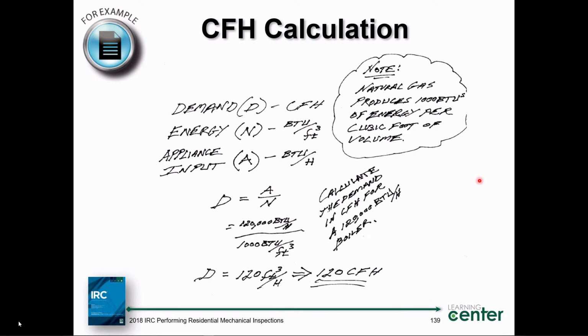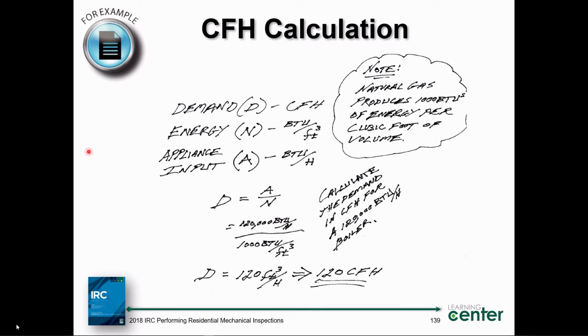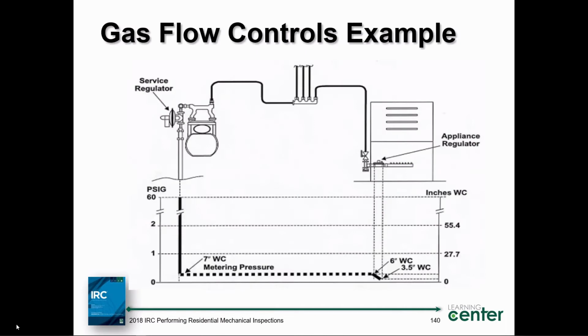Now that you know how to convert, let me show you a pressure profile of how we distribute gas in our homes and in our commercial buildings. I want to show you this, okay? First things first, this is a low pressure system. Why do you think I went over that water column measurement with you this morning? Because what we're going to ultimately end up doing is reducing the gas pressure to something low enough that's acceptable to supply our appliances with.